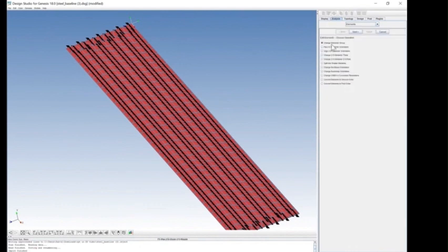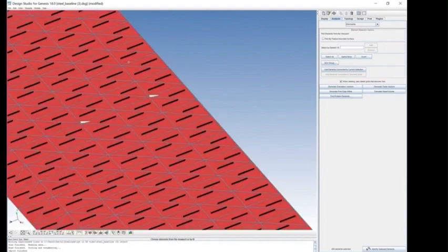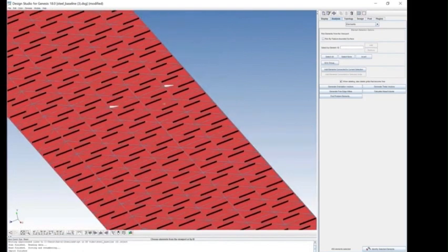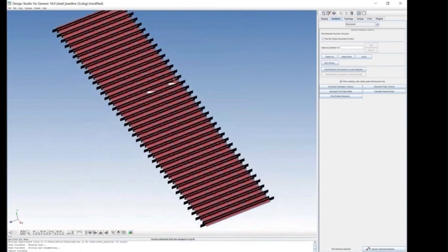We just go to analysis, elements, modify, change 2D theta. Let's use the vector by 2 grids. So let's choose the lateral direction. Next, finish. If I now go to generate theta vectors, I can see that the fibers are running widthwise. So if I were to create the model like this, E1 would be lateral along the width of the structure, but we don't actually want that.